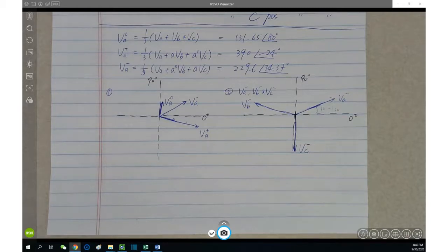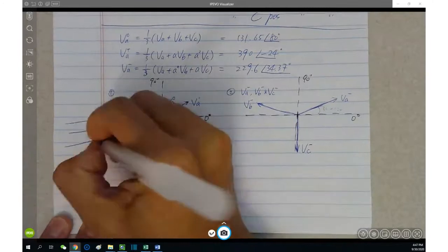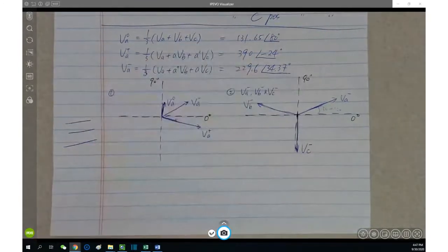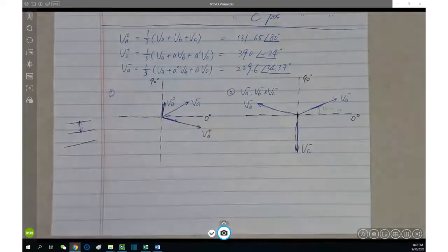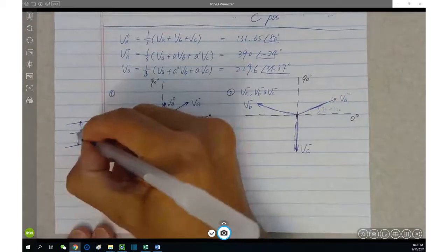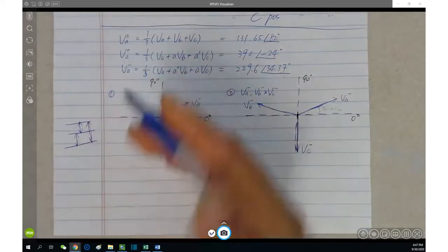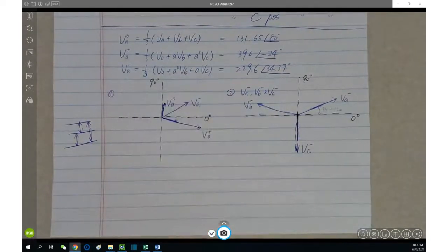But if that is the case, then there's one solution. When I did this experiment many years ago, I created a neutral point by using very large resistance. So you have three lines, right? Yes. Technically, you can only measure the line to line voltage, here to here, here to here, and here to here. But there's no neutral point for you to access. You can't find the phase voltage, right?